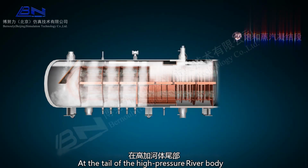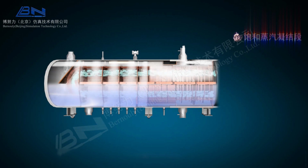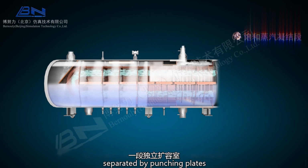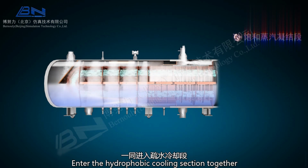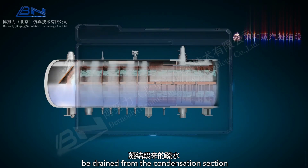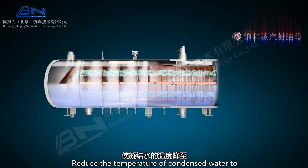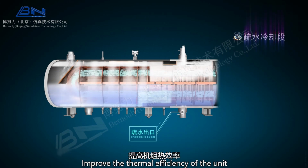At the tail of the high-pressure heater body, the upper-level drain water enters the drain chamber, an independent expansion chamber separated by punching plates. After expansion, it joins the drain water from the local heater and enters the drain cooling section together. The drain cooling section is fed from the condensation section and continues cooling, releasing heat to heat the feed water. This reduces the temperature of the condensed water to below the saturation temperature and improves the thermal efficiency of the unit.